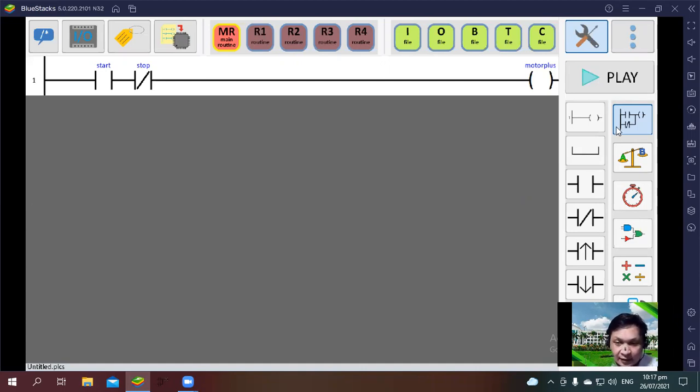All the other items above I0.1, I0.2 and above, can already be used as analog inputs. So in this case, I prefer to use start and stop as my switches rather than analog inputs, because these are hardwired to the interrupt pins on the processor itself.